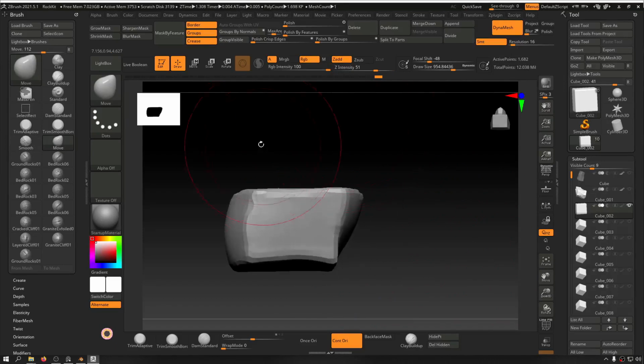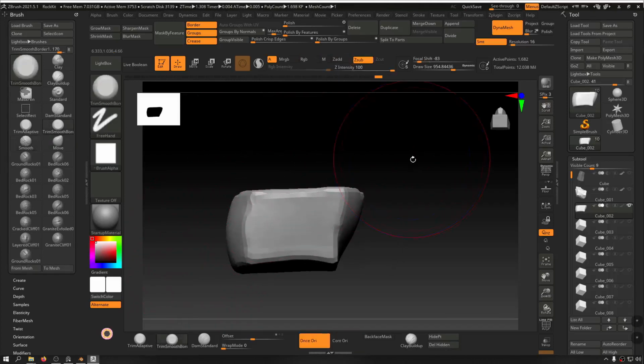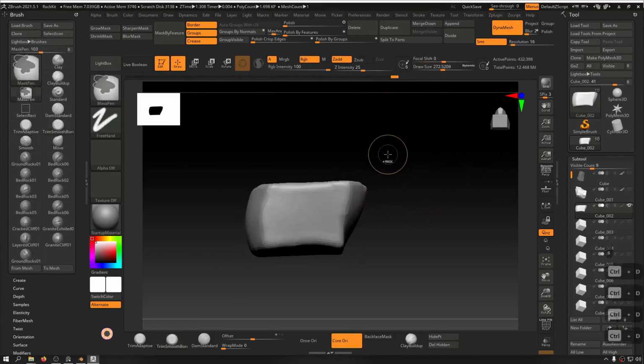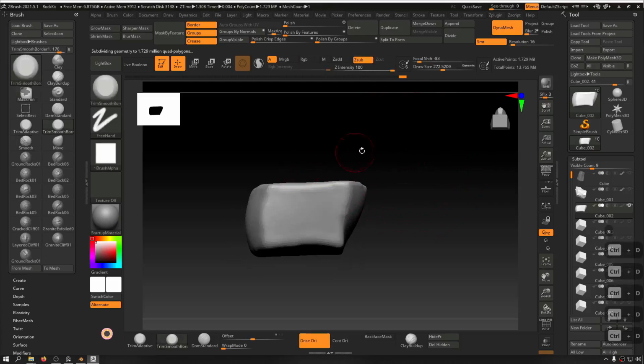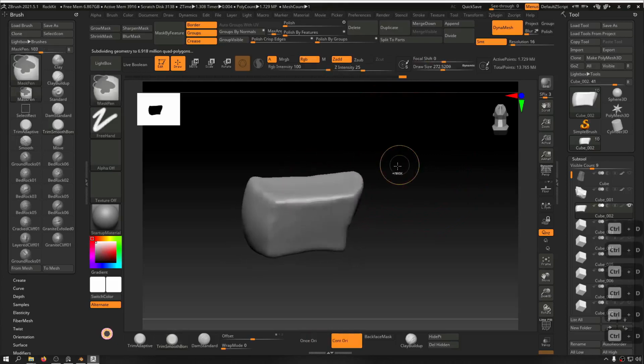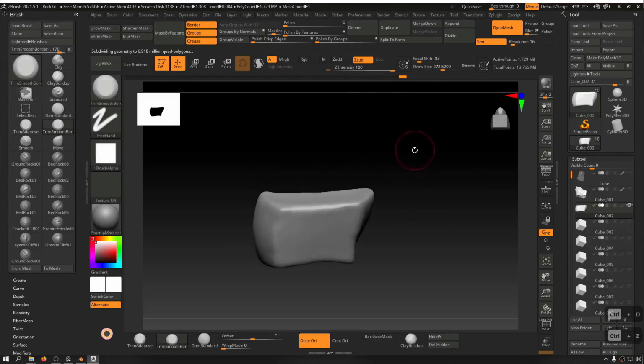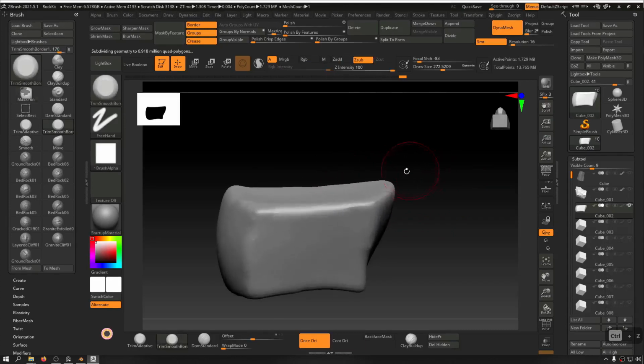And now it's time to take the trim smooth border and start to manipulate the shape. Okay, let's take this one. And of course, to get the best quality, we need a lot of resolution on this. Okay, a million piece is enough for this one, I believe. We really do not need 6 million polygons for this. Okay, let's use this. And again, as always, try to save incrementally, not to lose any progress.